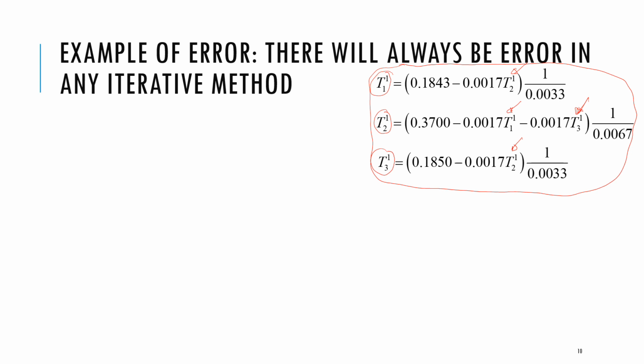So in this case, I chose, because it was a heat conduction problem in a slab, a transient heat conduction problem that has an initial temperature given, that initial temperature I thought would be a good initial guess, because if it's a heating or cooling process, it is likely to stay somewhere close to that, especially in this bio application.